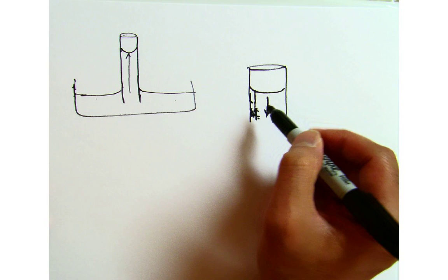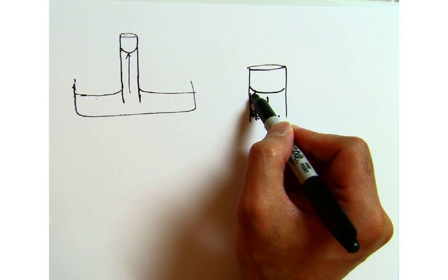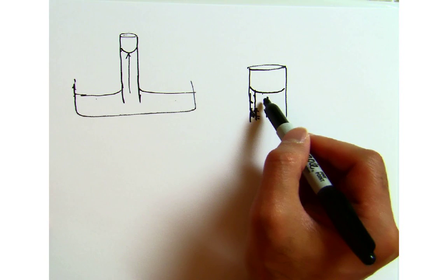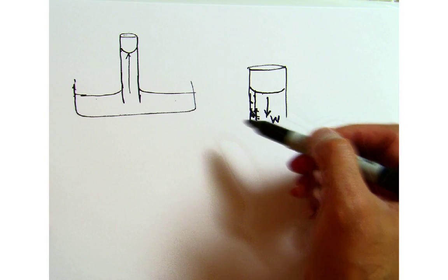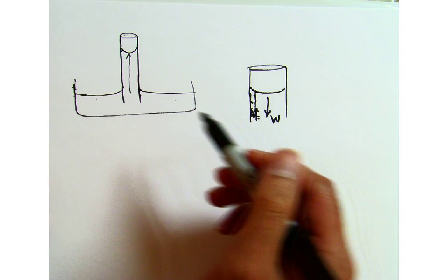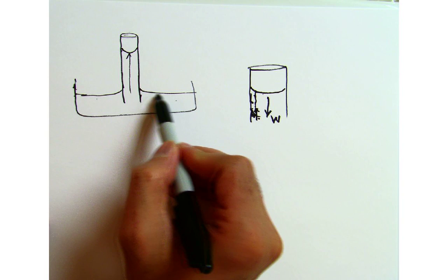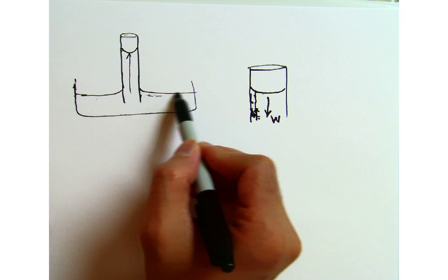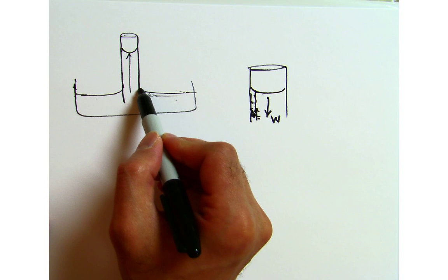Okay, so this is an important concept: the surface tension force is pulling the water up, but only to a certain extent. After a while the weight of the fluid counters the surface tension force, and after that you cannot pull any more water. Why did that not happen in the earlier case? Because over there it has to pull a much larger quantity of water, so there is only a slight bulge.